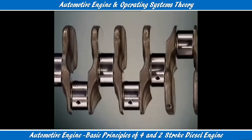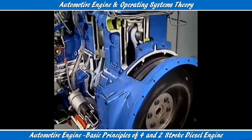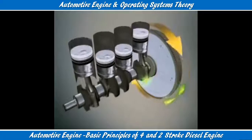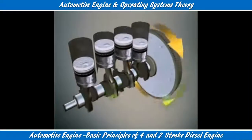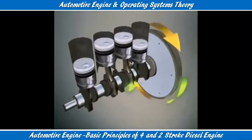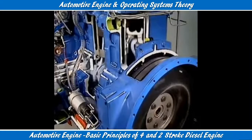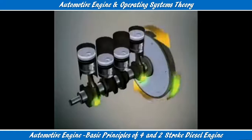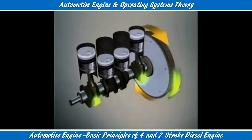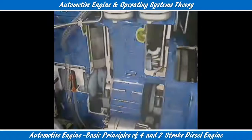On the rear of the crankshaft of both the four-stroke and two-stroke diesel is a heavy flywheel. It stores energy from the power stroke and gives it to the crankshaft to help it keep turning. In a four-stroke, only one stroke in four delivers power. The energy from this one power stroke has to turn the crankshaft through the other three strokes. Without a flywheel, the crankshaft would slow down and stop. In a two-stroke, the same principle applies, but every second stroke delivers power. A connecting rod links the crankshaft to the piston.